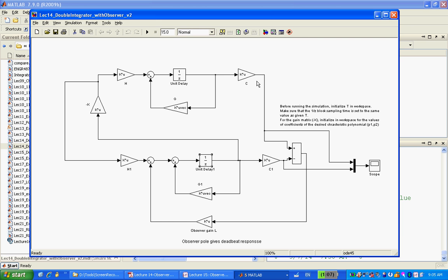Implement whatever you want, whether PID or this one here, or in the future some other optimal control techniques, using Simulink or an M file. Do the simulation first. I would recommend using Simulink because the program down there is a Simulink program. Then you go there and implement it. You don't do it if your simulation is not running well. As long as the simulation is running well, you almost guarantee that the experiment will be okay.